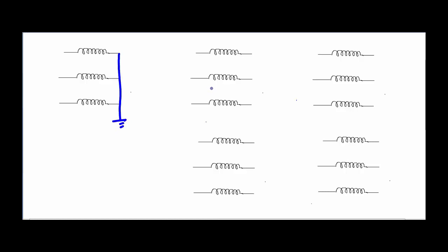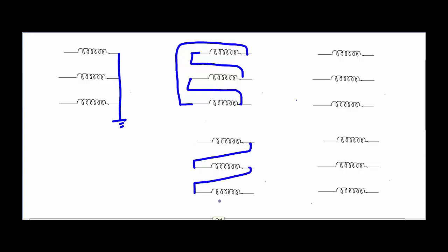And if somebody says that the low voltage side of the transformer is connected in delta, then that is a very big concern, because how we are going to connect the delta is quite challenging. We can connect delta in this way. So this is a widely accepted delta connection and there is nothing wrong in it. But what if we connect delta in this way? This is also a widely accepted delta connection and there's nothing wrong in it. Both of these two windings are connected in delta, but both of them are quite different from each other.